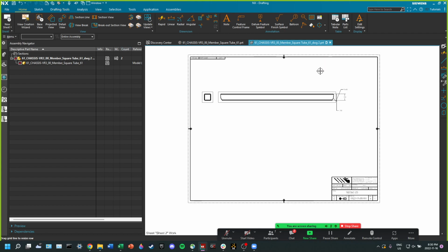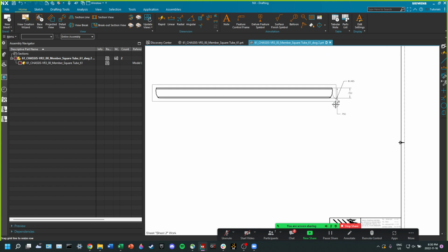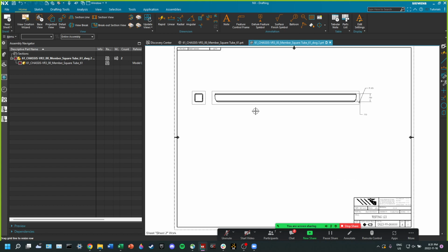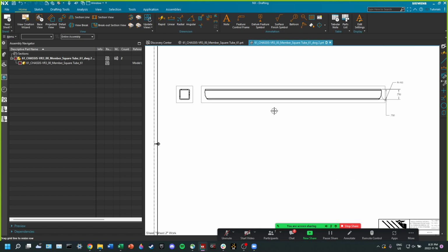Can you show us how this dimensions for us? Because in SolidWorks, I've always just let it dimension for me and then get rid of a few things and add a few that it doesn't take. When you do very complex stuff, yeah. No, I'm not showing you that. Dimension properly, go through and make your drawing. Don't just auto do it. It's better practice to go through and do all your dimensions.